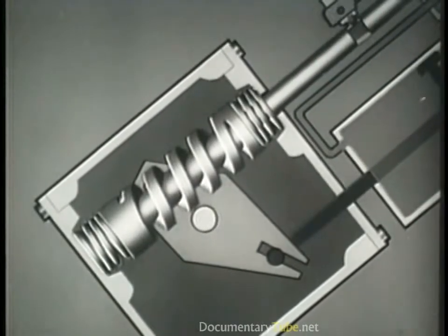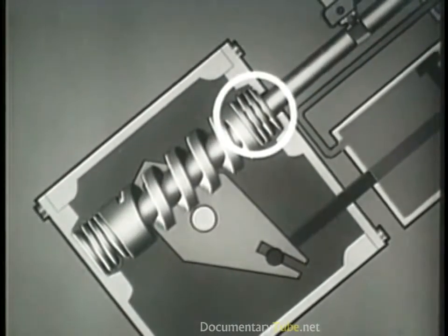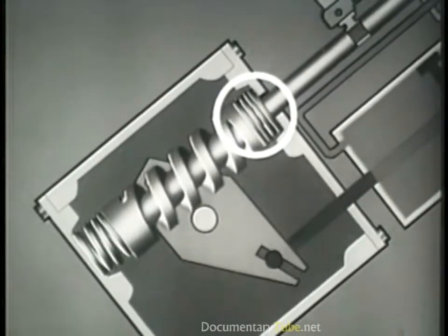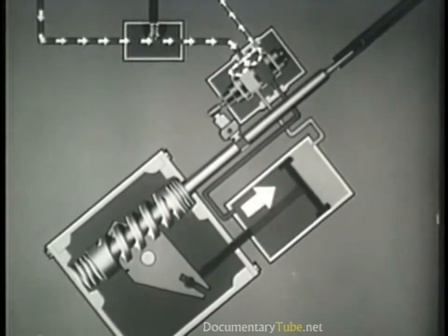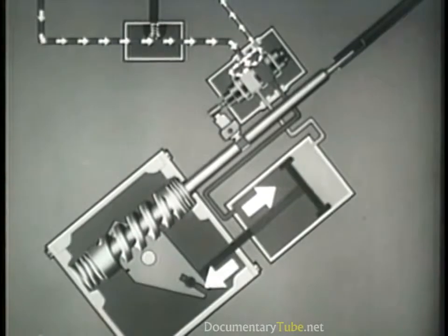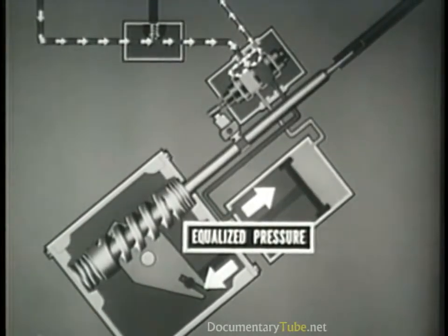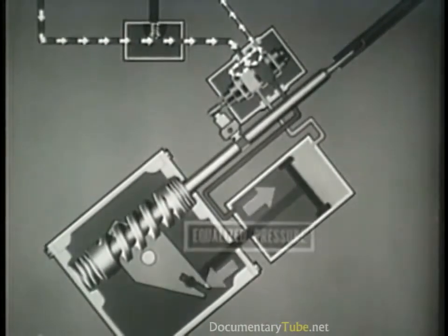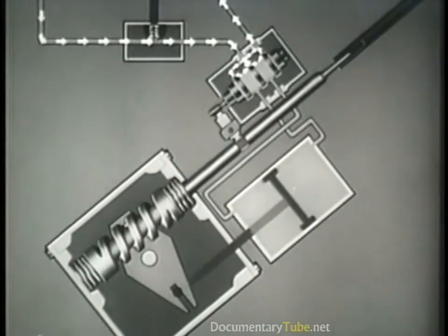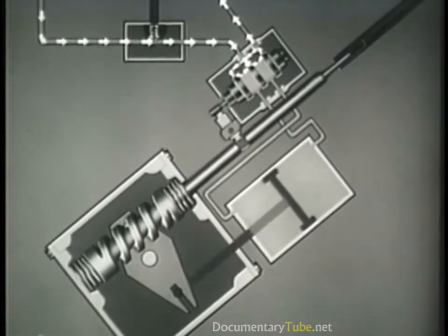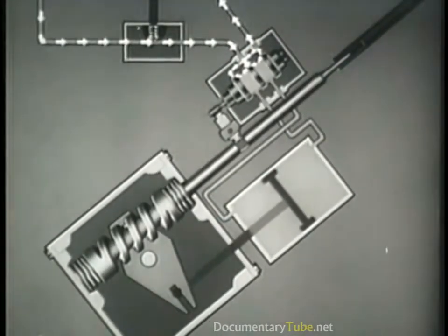These two opposing forces cause the steering cam to partially compress the upper cam spring. This also moves the control valve linkage and positions a valve spool where fluid pressure will equalize the force exerted by the steering geometry acting on the piston rod. The front wheels can then be held in any desired degree of turn. On return to neutral, all fluid from the pump is directed back to the reservoir. The pressure is lowered throughout the hydraulic system, and the piston and piston rod do not function.